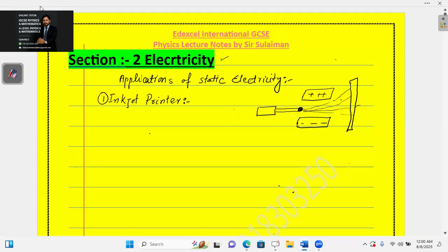The ink which is not required on the paper is deflected directly towards the storage bag named the gutter, and it comes back. A voltage is applied to the plates. One is negatively charged and the other is positively charged, with voltage provided from the positive and negative terminals of a battery. The droplets are attracted to the plate of opposite charge and repelled from the plate of the same charge.